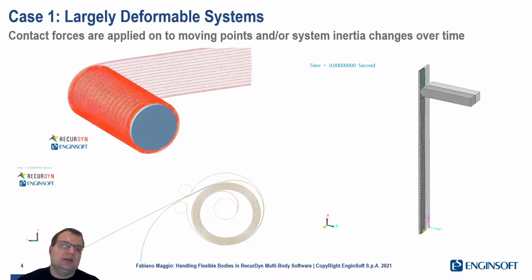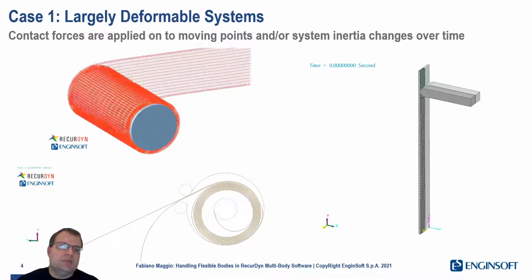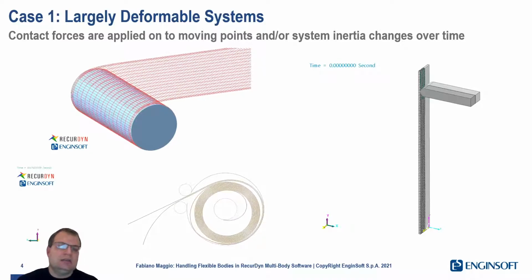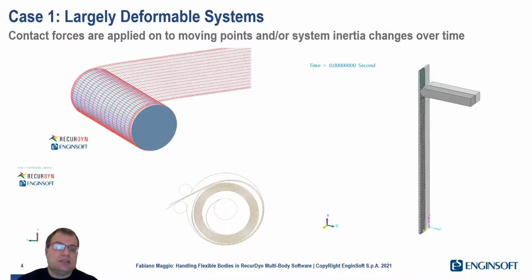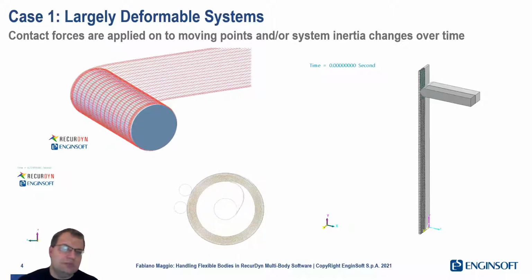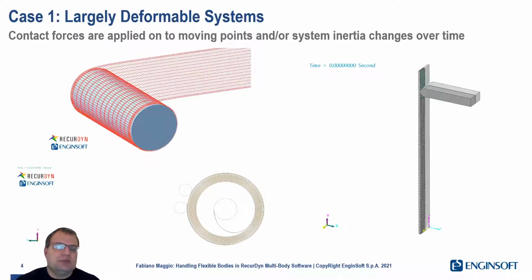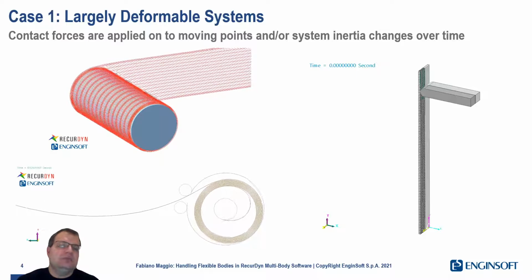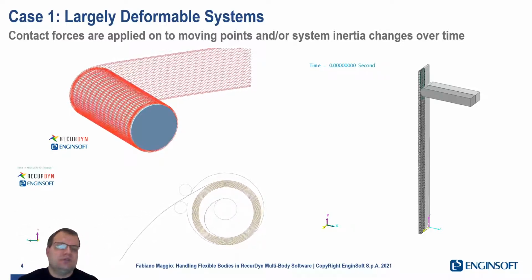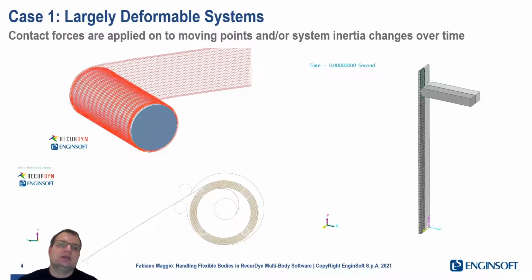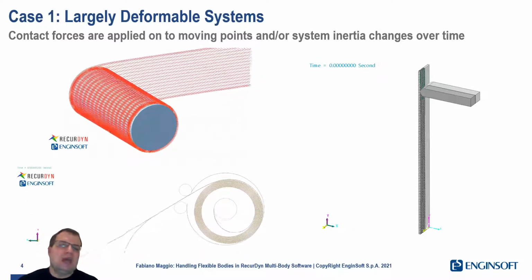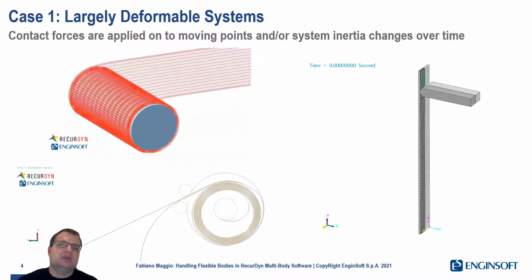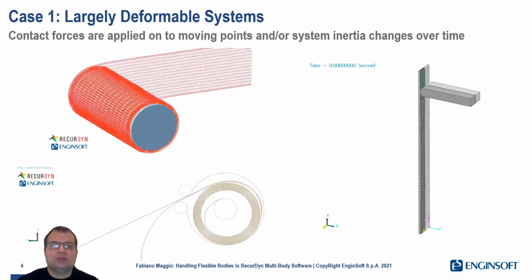On the right beam, I have a rigid body, and I placed in the constraint a spring, so lambda approach. And this rotational spring has the stiffness that you might calculate analytically for a beam. It's a cantilever beam, so all the formulas are well known. On the left, I made the same beam, but it's flexible, and I used one of the formulations available in RecurDyn. So the two beams should behave in the same way, because one is fixed, the other is fixed through a spring, but the spring has the stiffness that is calculated properly.